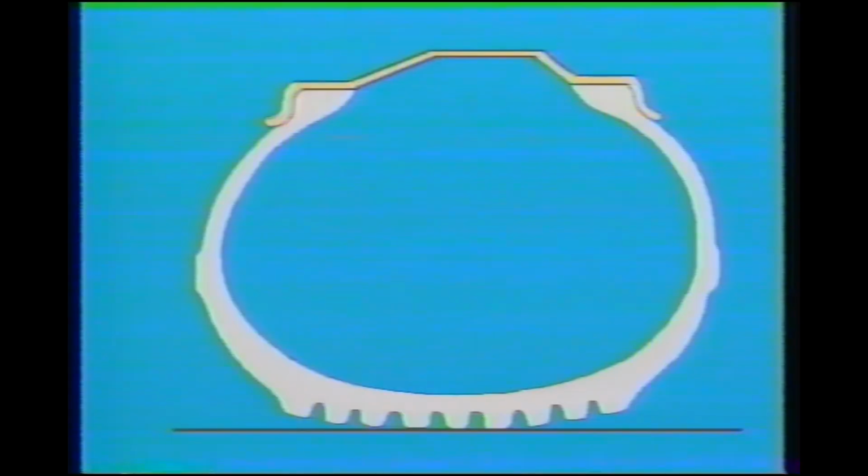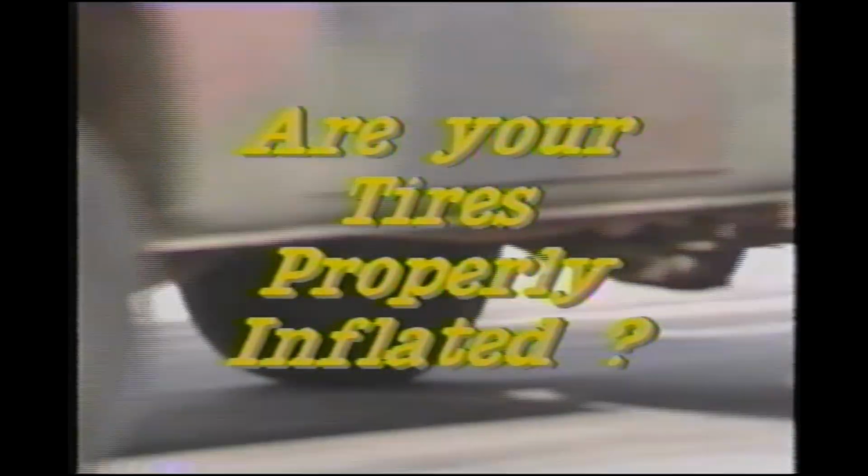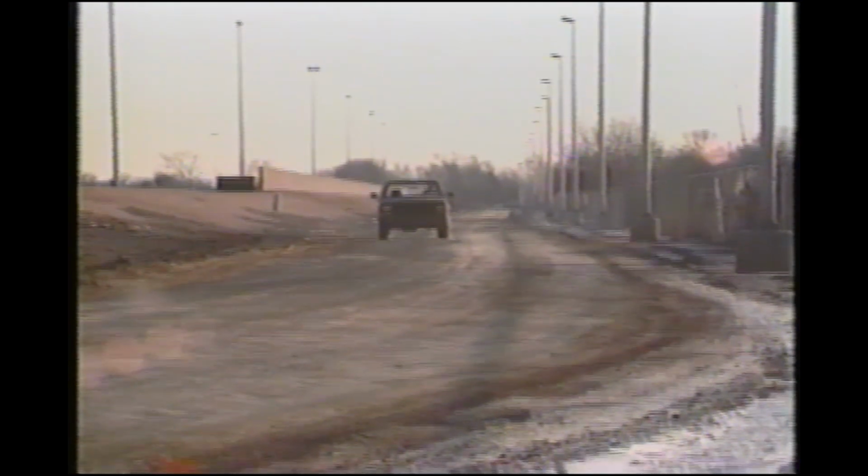An underinflated tire will be worn on both edges. When a tire is overinflated, the pressure causes the center of the tread to expand beyond the sidewall height, again resulting in a loss of traction. An overinflated tire will be worn in the center of the tread. In either condition, traction is reduced, imposing a potential hazard while reducing tire life.